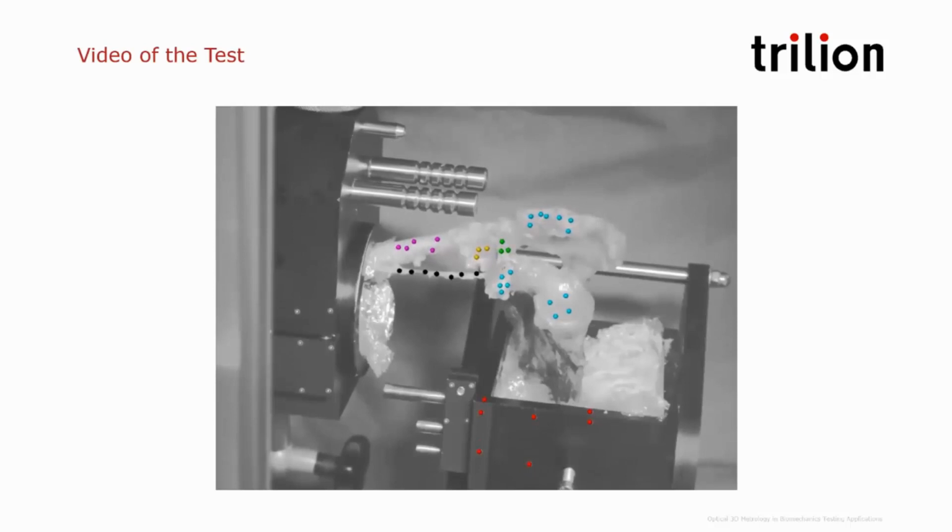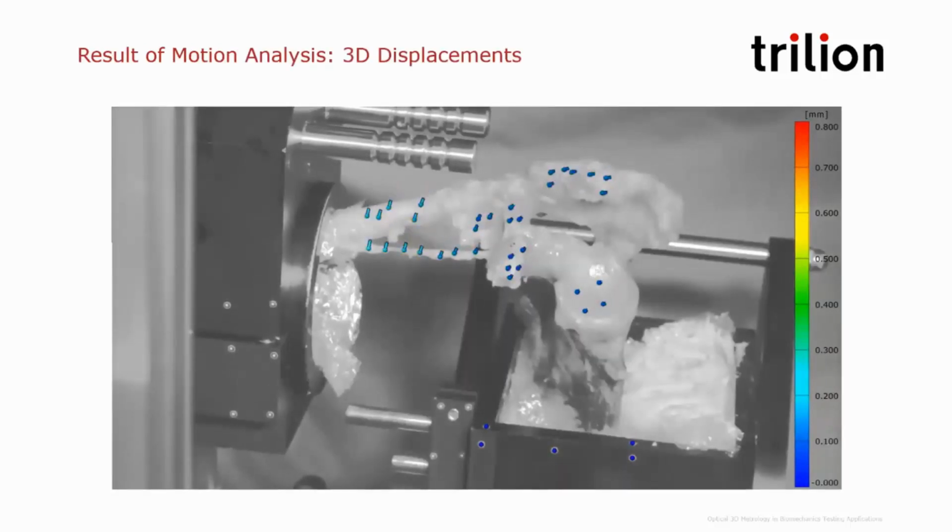Let's take a look. Here's a typical resultant data analysis from one of our projects. Okay, you get 3D vectors showing direction and magnitude, and because we have target dots throughout, we get a holistic measurement that's really intuitive to see. So with regard to the magnitude here, these are really small displacements from 100 to upwards to 800 microns, but certainly some of these points are very, very small, and we're able to see that.